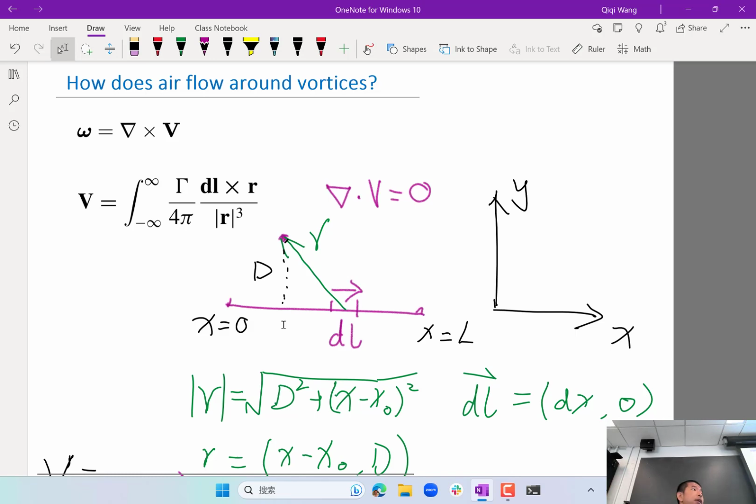This is because usually away from airplanes, right? If you look very close to airplanes, if it travels significantly faster compared to the speed of sound, you get compressible flow. But when you look at, for example, the wake of airplanes or locations that are sufficiently far from airplanes, the velocity field compared to the speed of the airplane is relatively low. So even if the airplane is traveling at a finite Mach number, the velocity field behind the airplane or sufficiently far away from the solid geometry can usually be approximated pretty well with an incompressible flow, right?